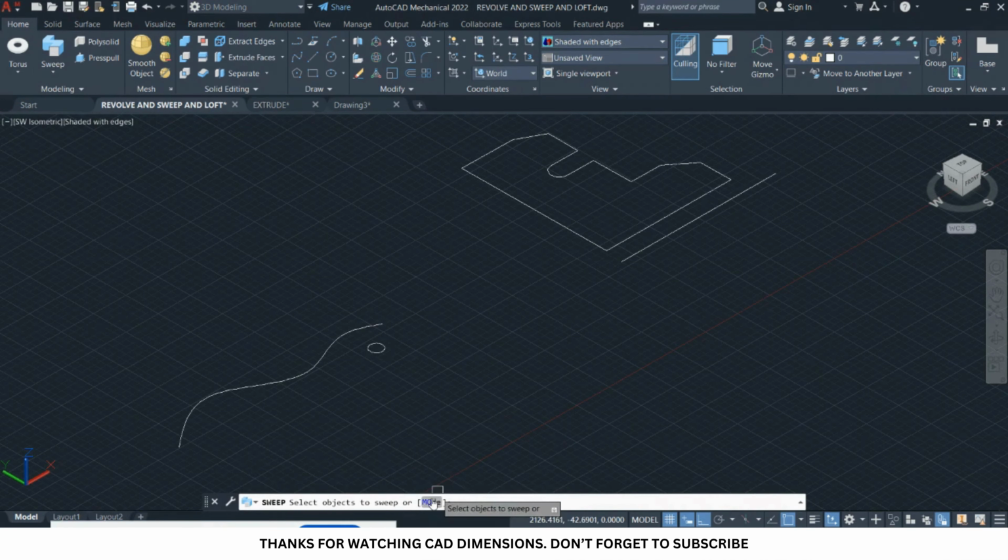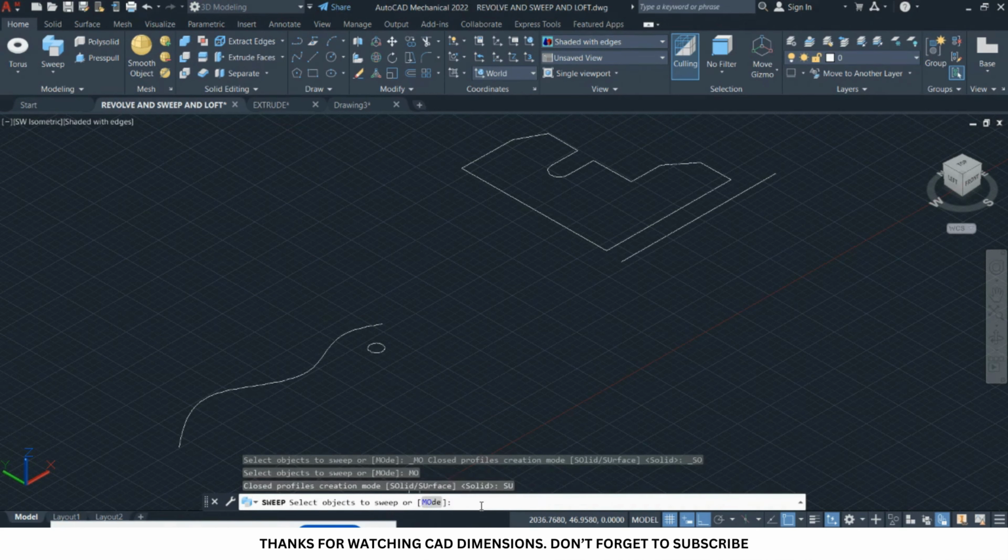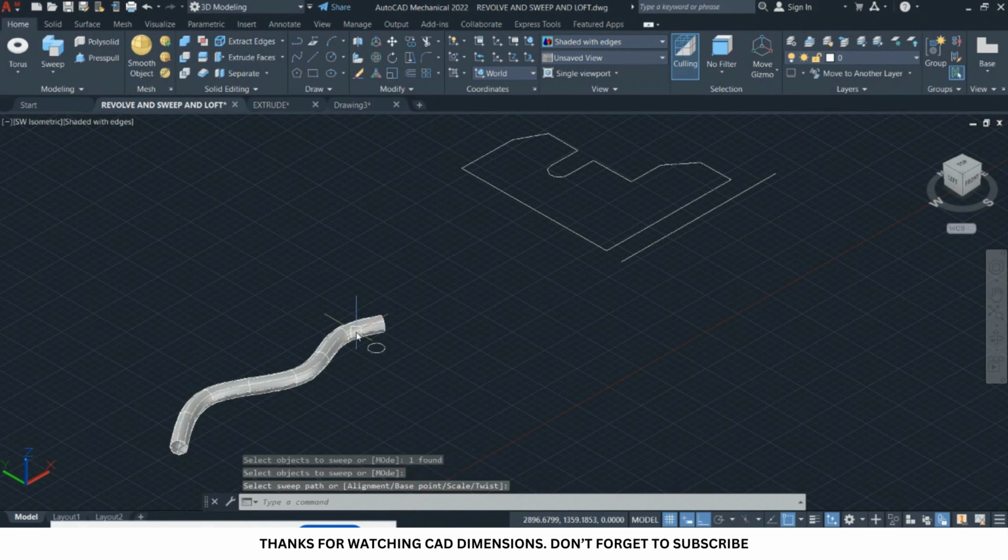For example, if you come to the mode, you can also create a sweep with respect to surface. That will create a hollow shape with the sweep. So I've selected the surface, select a circle which is a closed shape, press enter, then I select this.